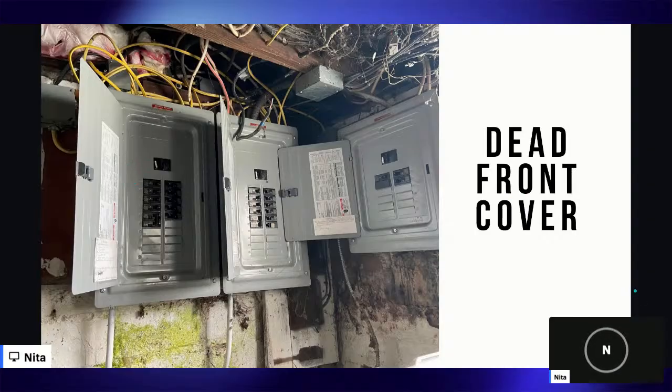This is basically serving as protection so that you don't accidentally touch any live wires and so that nothing can get to your wiring. The openings in your dead front allow the handles for your breakers to come through. So during an inspection, if safely possible, you want to remove the dead front cover because you need to be able to see the wiring.